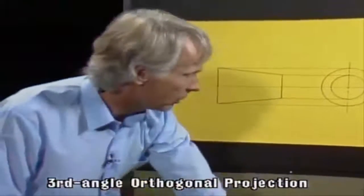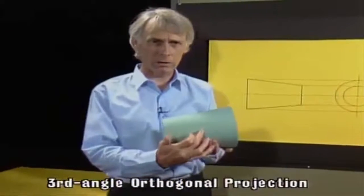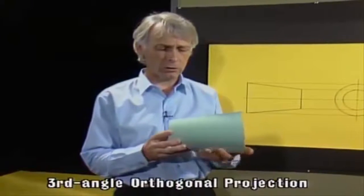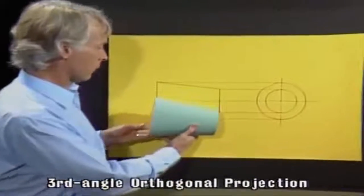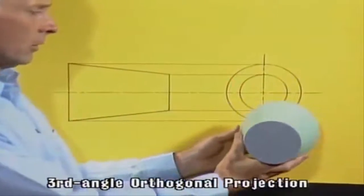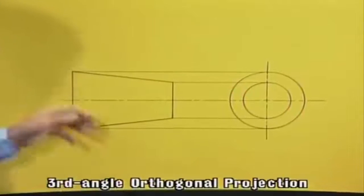Finally, the projection symbol is based on a truncated cone. We accept that as a front elevation looking in that direction. The end elevation is always chosen so we end up with 2 concentric circles. Okay, we've got the front elevation there. We rotate that round to have 2 concentric circles. The 2 concentric circles are shown near to the narrow end of the truncated cone.